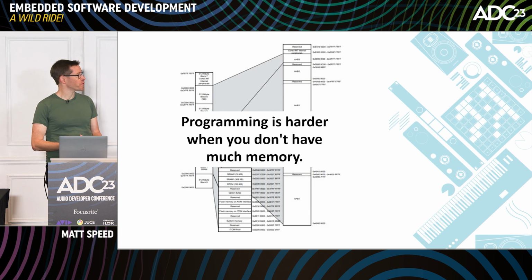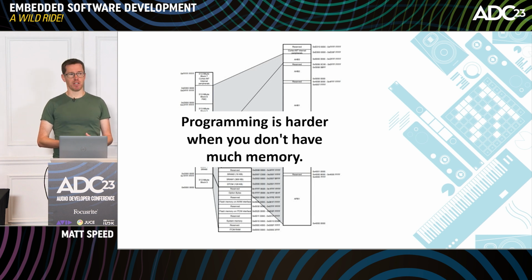It's a similar story with flash. Flash memory, you're probably going to have a few hundred kilobytes on the device, if you have any at all. It's not uncommon for simple microcontrollers to have no flash memory, that's non-volatile memory, and just have to go off chip.